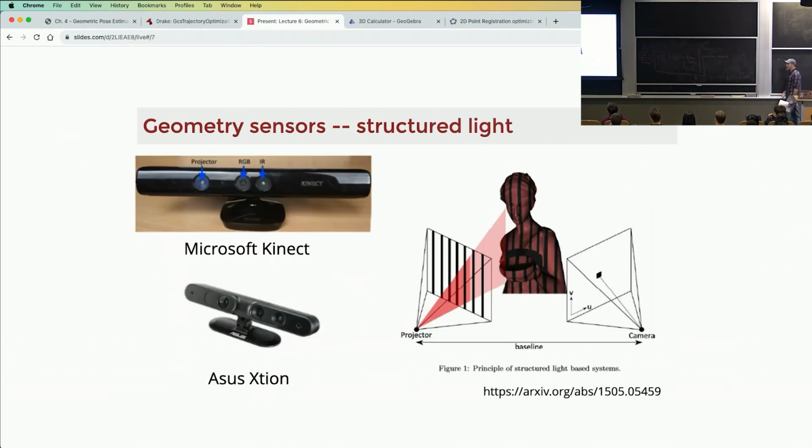Okay, another line of tools like this, the Kinect sensor was a big deal when that came out. Not only because it worked very well, but because it was so inexpensive, right? So somehow the home entertainment gaming world kind of revolutionized robotics by building a sensor that we needed. Okay, that was fantastic. The first version of Kinect worked with structured light. So it's actually about as simple. I mean, this was an idea for decades and decades, okay? But it became practical with the Microsoft Kinect, where you actually just project patterns. The patterns will deform on the object.